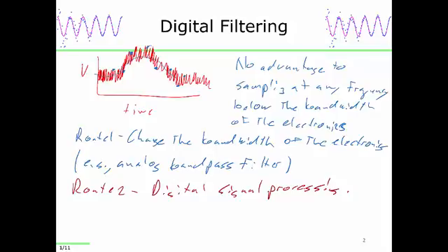So what ideas, without knowing anything about digital filtering, just intuitively, if you looked and made this measurement, what would be the first thing you'd be likely to try to reduce the noise from that original red trace? Average, right? There are two obvious ways of doing it. The first way is binning, right? Every 5 data points, just turn that into 1 data point. Another way is for every pixel, just write the average of 5 and then move that 5-element average across the data.